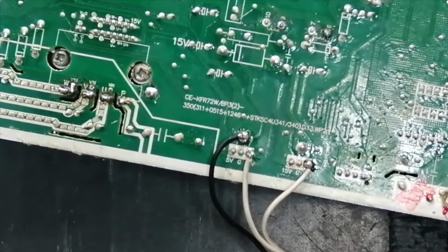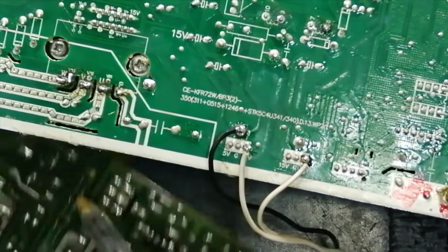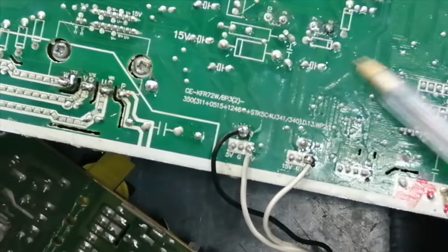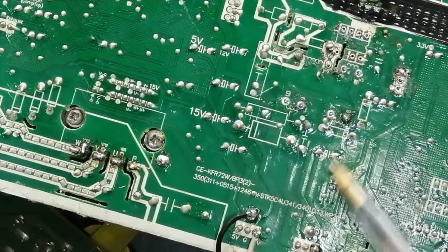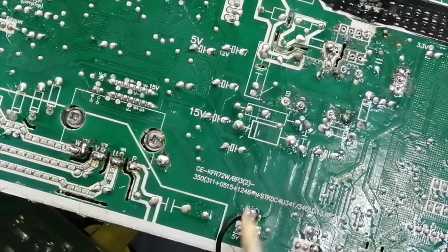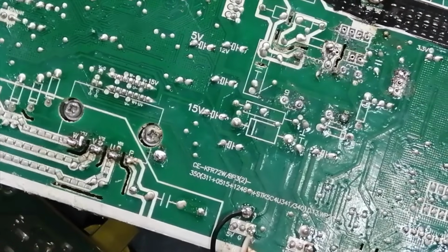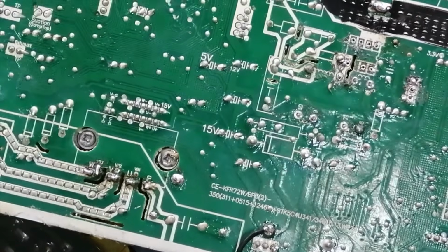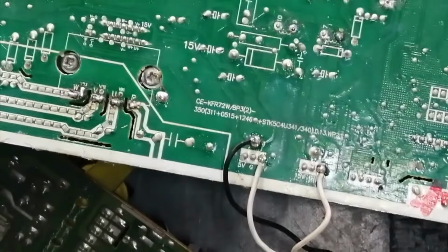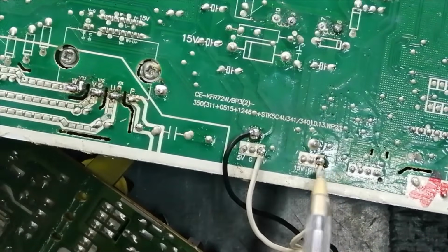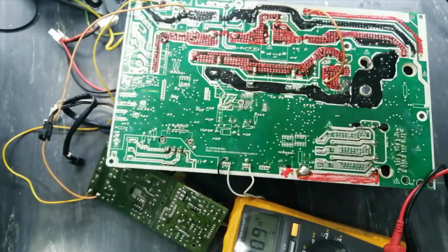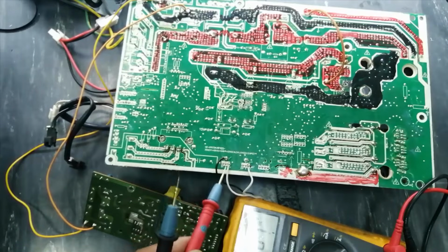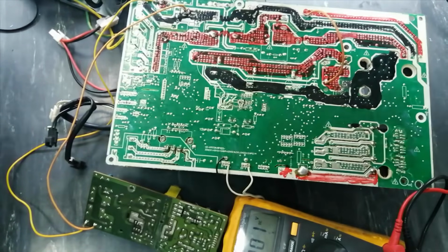I got 22 volts from this power supply and 12 volt to this power supply, as this SMPS gives us 12 volt and 17 volt at this point. 12 volt is regulated into 5 volt and 17 volt is regulated into 15 volt. So I connected 22 volt here instead of 17. Now I will connect power, because this external power will take 220 volt, and I made common ground for the board with both power supplies.